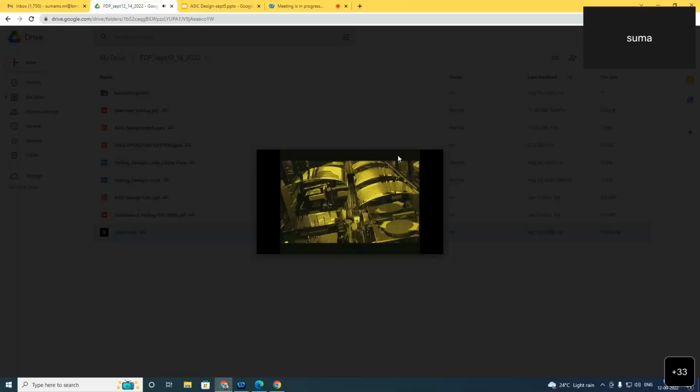These are known as VLSIs. Here, extremely intelligent, fully automated machines are used to apply the light-sensitive layer of lacquer to the oxide on the slices and to expose the slices. No light is used in these rooms, as the lacquer is not sensitive to this.